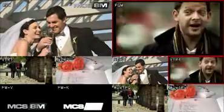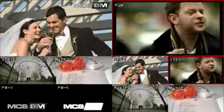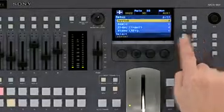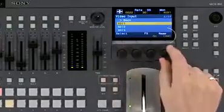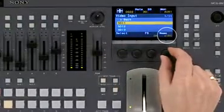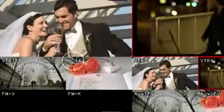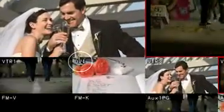It is crucial to name sources, as they will be visible on the multi-viewer. To do this, go to System, Inputs, and scroll through the list of preset signal names. You can see that as SDI1 is changed, the source name is updated.